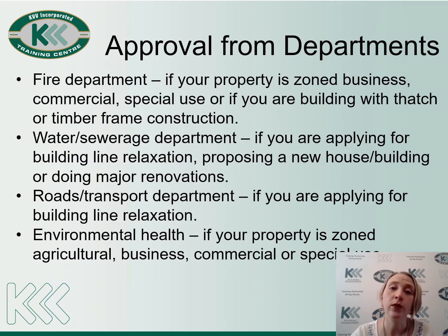You may also need approval from the other departments in the municipality. The fire department will have to sign off if your property is zoned business, commercial, special use, or if you are building with thatch or timber frame construction. Water and sewage will have to sign off if you are applying for building line relaxation, proposing a new house or building, or doing major renovations. Roads and transport also need to sign off if you're applying for building line relaxation. And environmental health will have to sign off if your property is zoned agricultural, business, commercial, or special use.